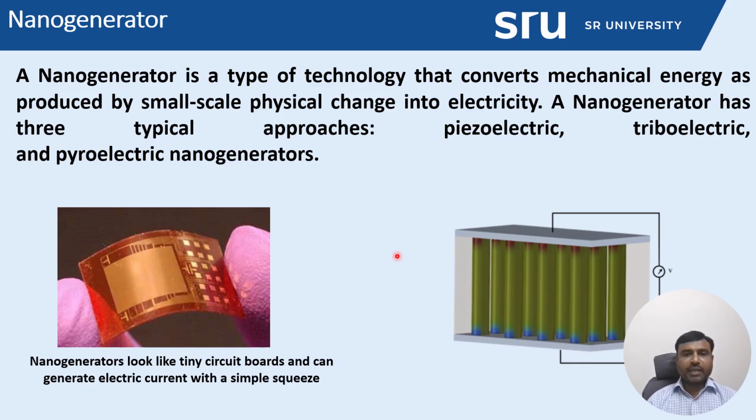This is the basic mechanism: in between the two electrodes we can incorporate the nano generator material, either piezoelectric, triboelectric or pyroelectric material. When applying a mechanical process, it produces some decent voltage. Based on the output voltage, we utilize the changes in the bioreceptor or biorecognition layer. Indirectly, it is correlated to how the biomolecules interact with the bioreceptor and how the voltage output is affected, which can be easily correlated for the detection of various compounds.